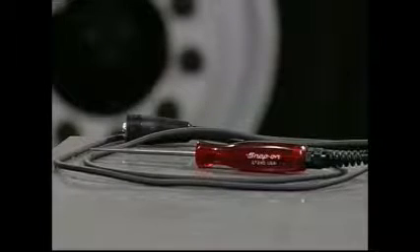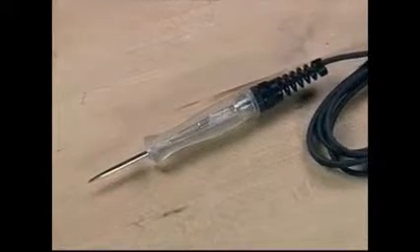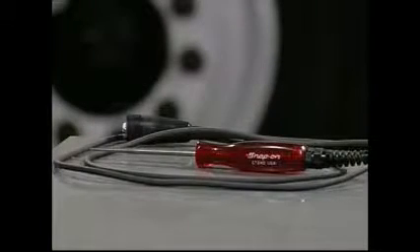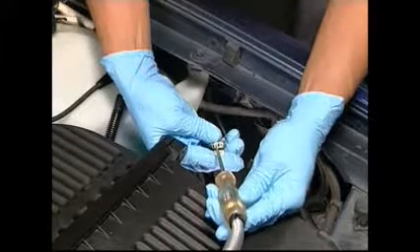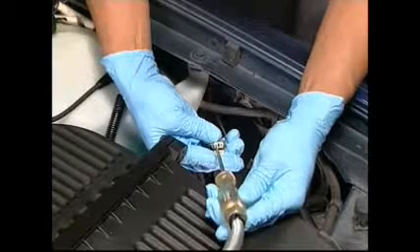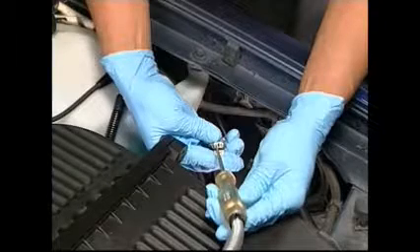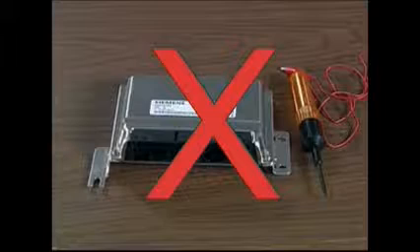Self-powered test lights are also known as continuity lights. They are used to check the continuity of an open circuit. Self-powered test lamps look similar to non-powered test lamps, but they have a small internal battery attached between a light bulb and two leads. With a self-powered test light, if the two leads are touched together or connected through a low-resistance circuit, the bulb will light because doing so completes a circuit between the bulb and the test light's internal battery. We can't overemphasize this point.